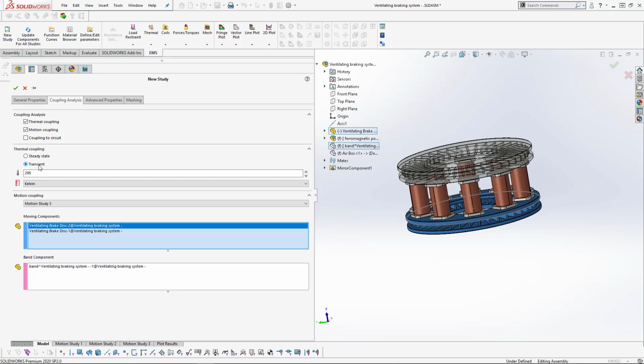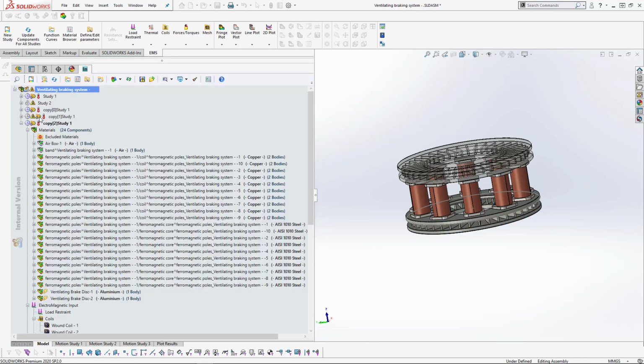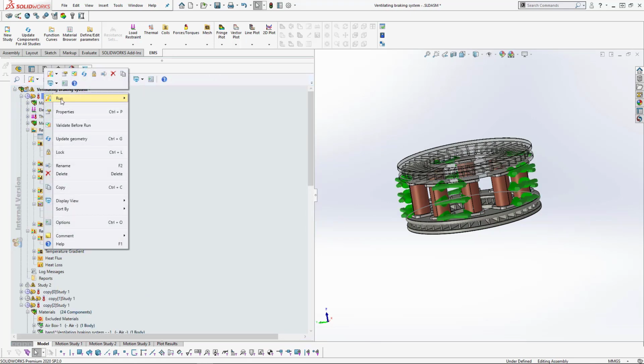So this is why, after finishing the magnetic simulation coupled to thermal, we have the option called continue thermal run only. We continue running the transient thermal simulation only. We don't run the EM solution again. Based on what we solved in the previous simulation, we continue the thermal simulation only. Let's suppose that we validate. I have some studies here, and as you can see, we have run all or continue thermal run only.